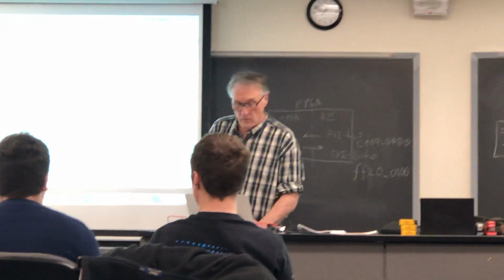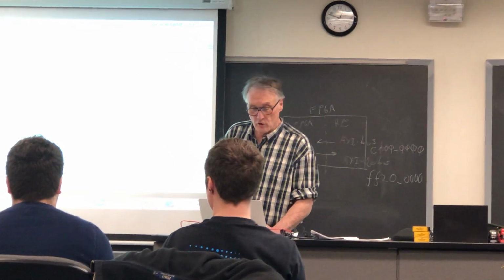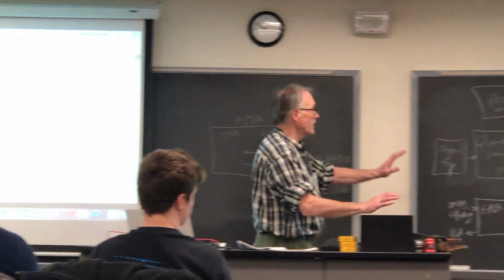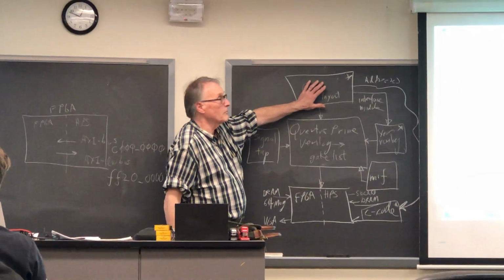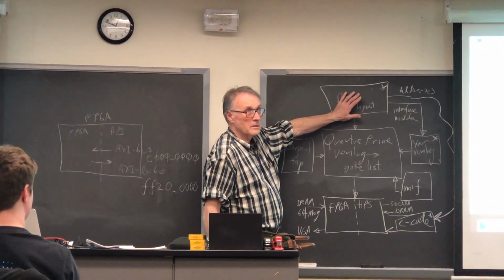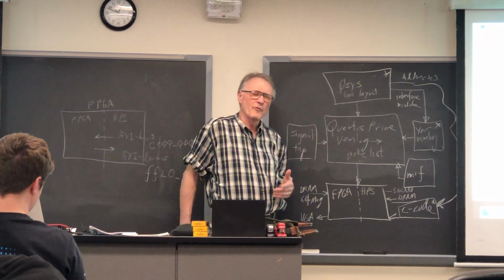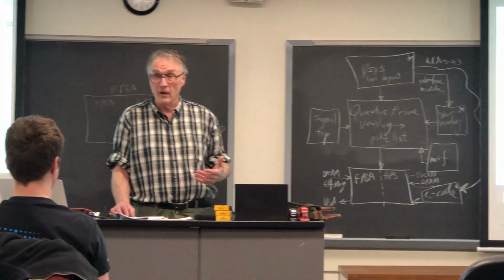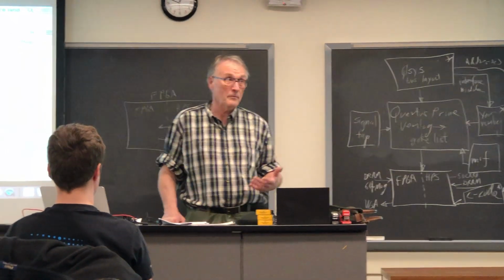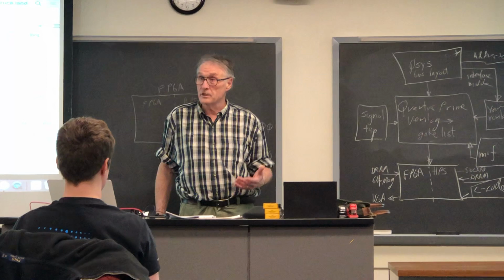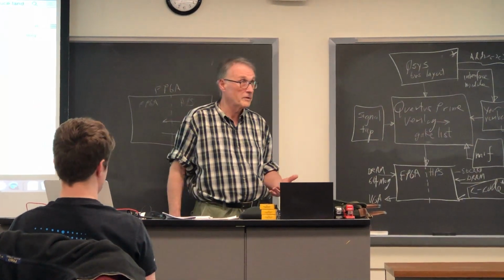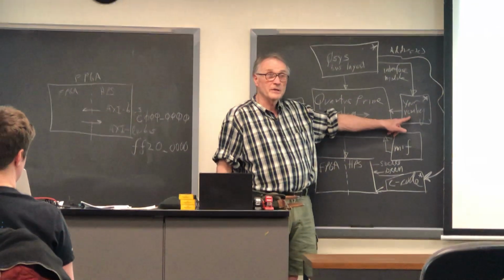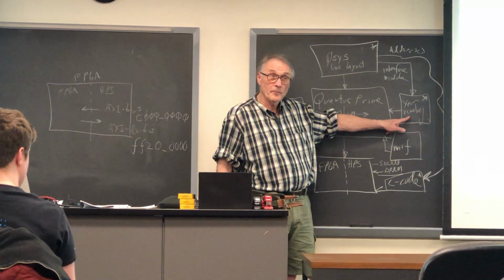So, for virtually every project, we're going to be specifying Qsys modules and addresses. Now, for this project, it's already laid out for you. You don't actually have to modify any of the VGA stuff for this project, for the Lab 1. You are going to have to add Verilog because your solver is going to go here.